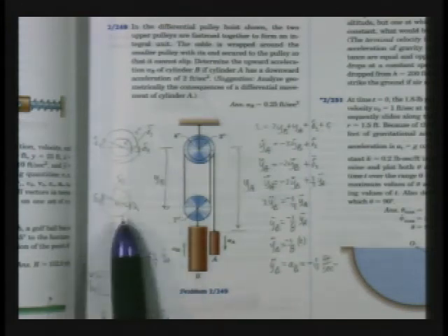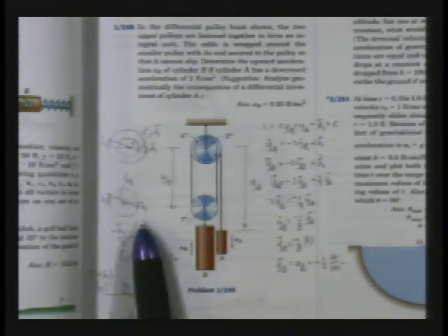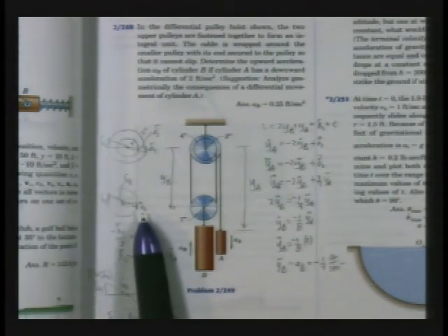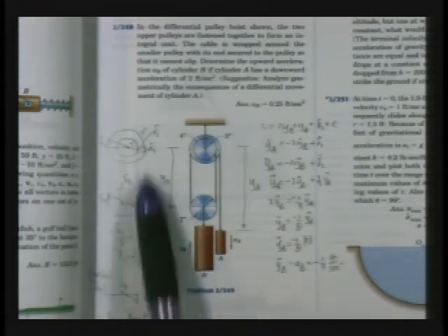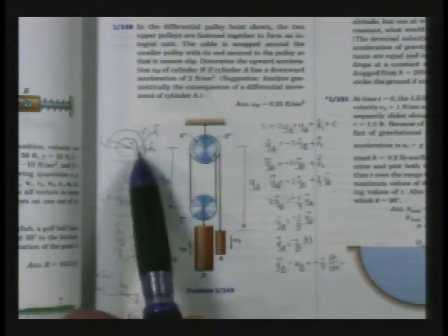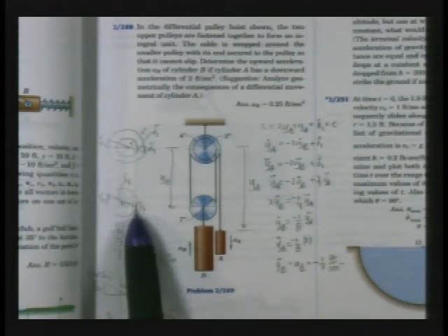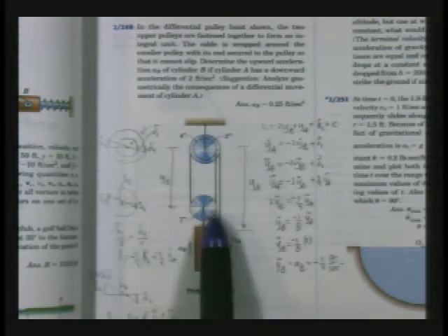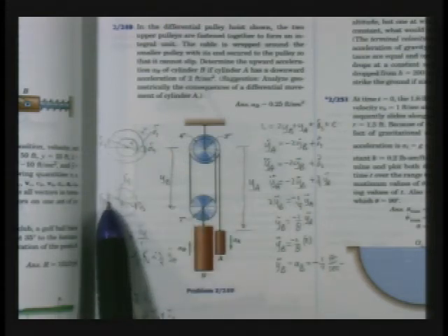Then here's the trick on following their solution. Down here, if we move to the lower pulley, then this 3-inch displacement right here has to match the 3-inch drop, or I'm sorry, delta 3 drop right here on this edge. And at the same time that's occurring, the far left edge over here is going to rise up by the amount delta 4.